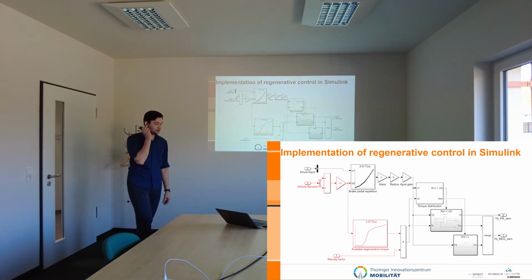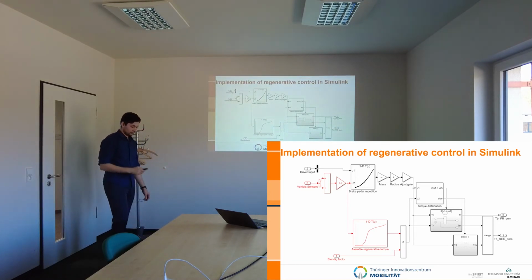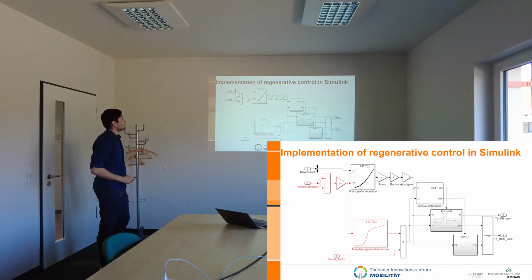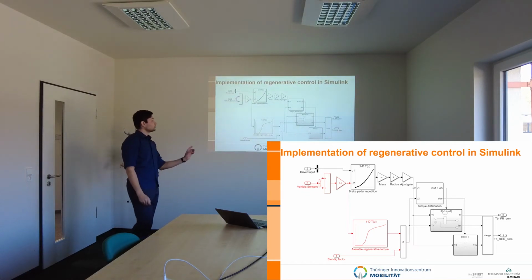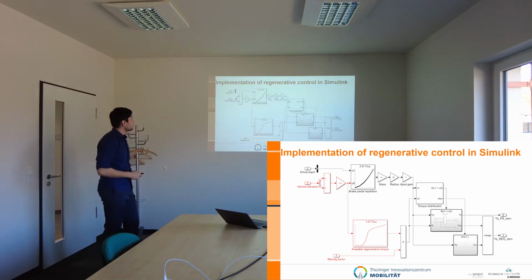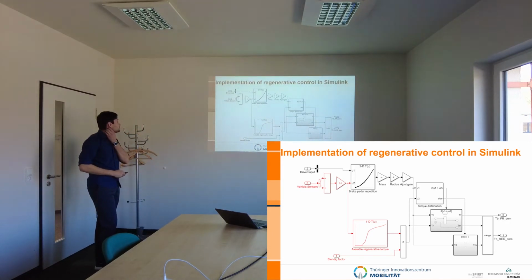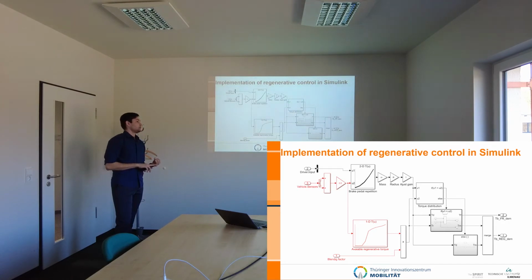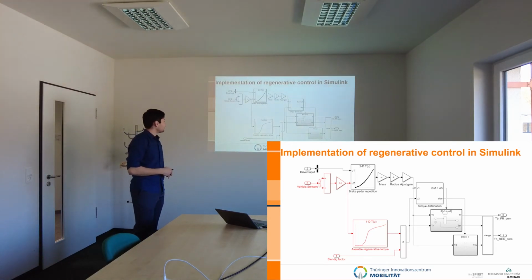The implementation was realized in MATLAB Simulink. It does the same as in the block diagram. We have 2 inputs, 2-dimensional and 1-dimensional lookup tables. Here we compare the demanded and available regenerative braking torques, and use the outputs for the torque demand, the motor torque and the friction torque. Also, you can see here the other inputs with the blending factor, which depends on the temperature of the battery and the state of charge of the battery, etc. And as I said previously, here 0.9 was used.